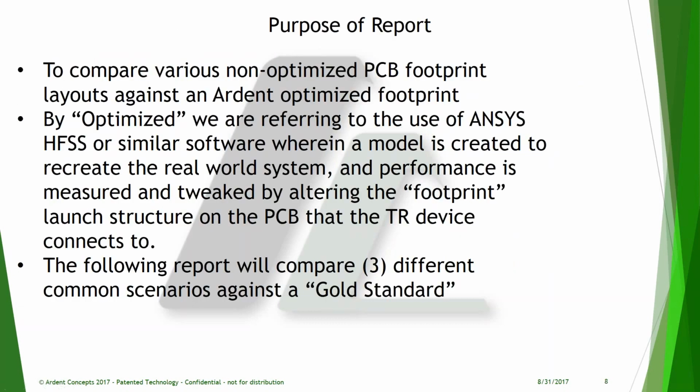So again, the purpose of this report is to compare these different launch transitions. Again, by optimized, we're talking about using something like ANSYS HFSS or similar 3D modeling software, where we create a model of our transmission line or our system to recreate the real-world system itself. We'll look at the performance of that system, we'll tweak it, and then we'll alter that geometry and measure again to make sure that we end up with the optimized footprint.